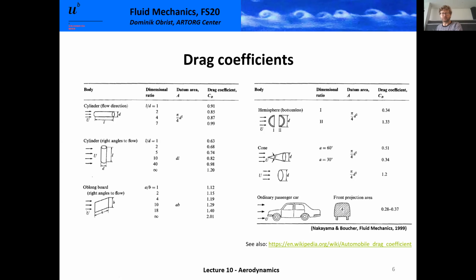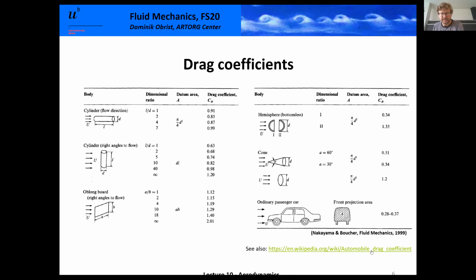So we have to be careful. If we have a drag coefficient, it needs to be multiplied by 1/2 rho u squared, u being the velocity of the car, times the cross-section of the car. That is often forgotten. Let us take a quick look at this link down here. This is a Wikipedia page. I need to change the, yeah, here.